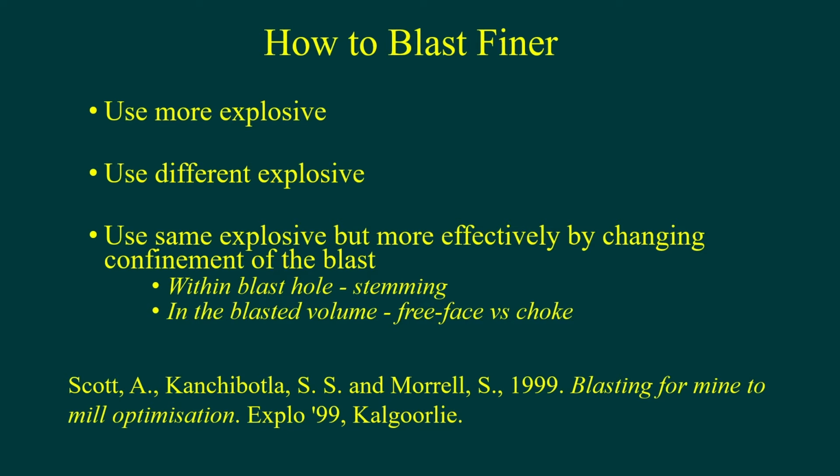So we're going to discuss a number of ways that you can blast finer. The first and probably the most popular way of doing that is simply to use more explosive. One can also choose a different explosive with different properties, and one can use the same explosive but in a more effective way by changing the confinement of the blast. And we're specifically going to look at stemming and free face versus choke blasting.